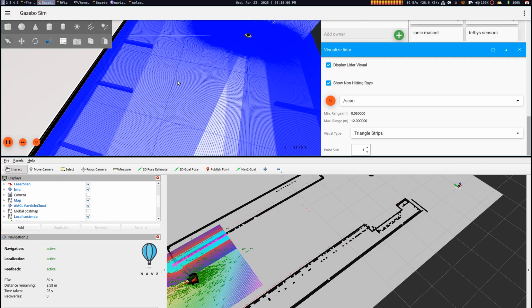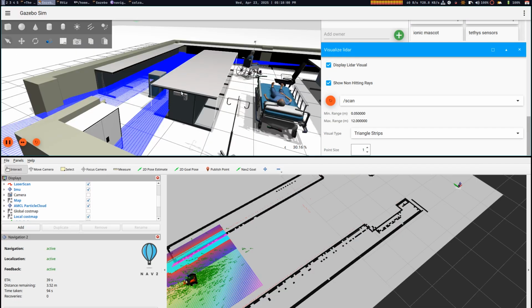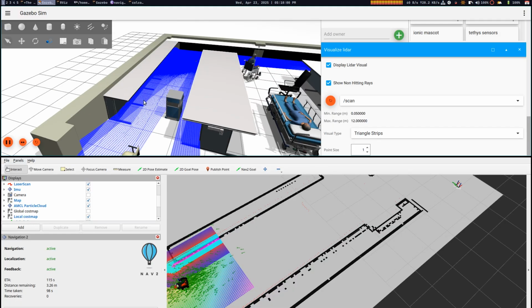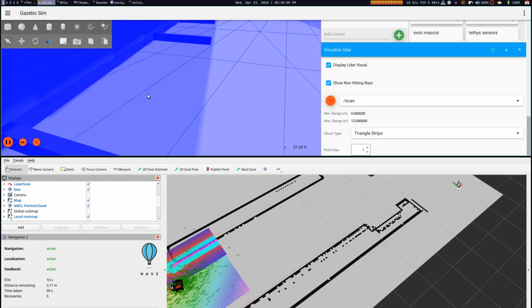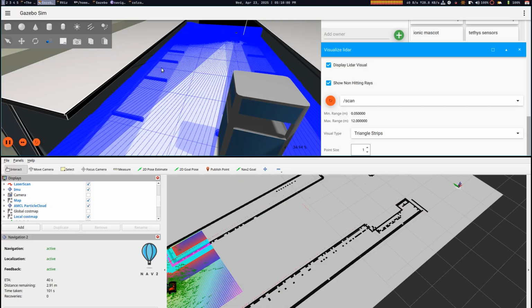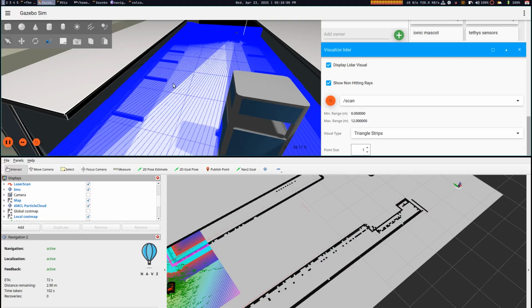So initially when I set the locations for these goals, I had put it inside, like the robot can go and enter inside, but then when the robot went inside, it would just maybe go straight, then get stuck here, and then the navigation would fail.